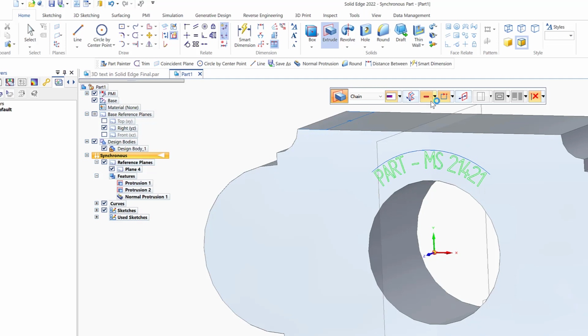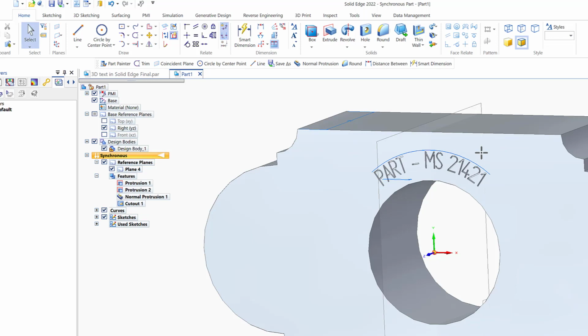It is a minus. Then right click. There's one here. So now this is outside. This is going to be taken outside, so I want to put it inside. Okay, but inside how much? 1.5 millimeter. Very good. So we were able to do the engraving along a curve.